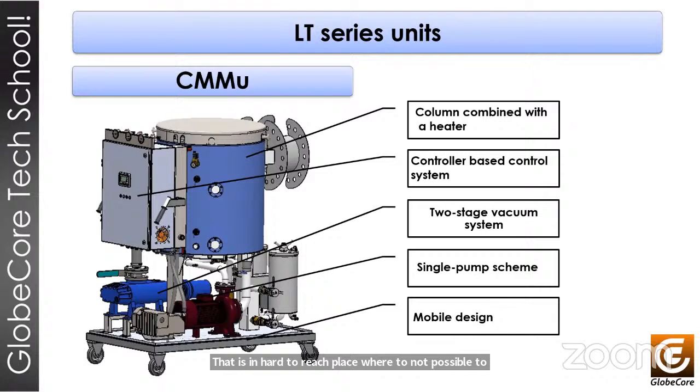Due to the use of more universal seals, filtering, and nozzles in the vacuum column, the equipment can be used to process not only transformer oil, but also turbine, industrial, and other types of oil.